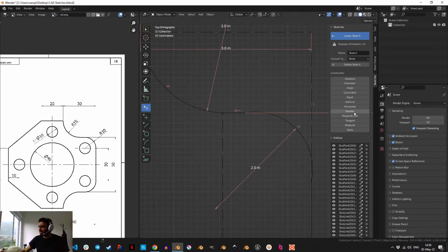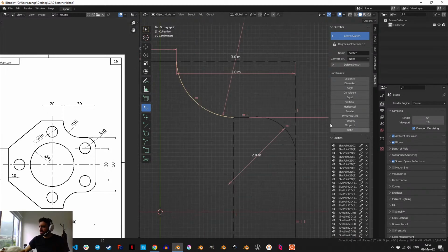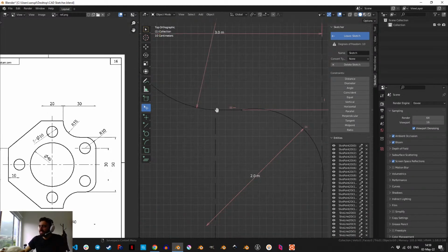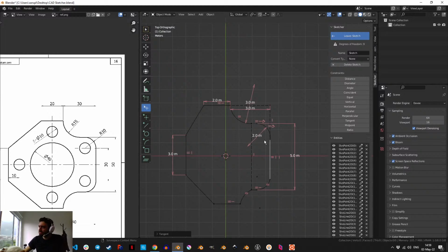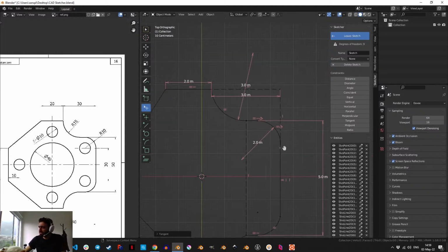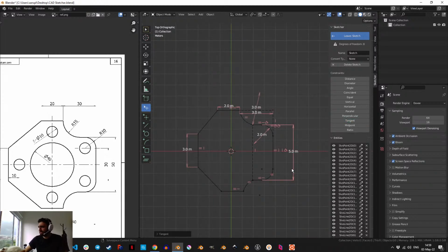Let's do it again. So tangent between this and this. Why isn't it working? Hmm. This works though. Maybe it's just over constraining. That's the problem. If I over constrain things, I'm gonna get into trouble. Here, I think we should add a tangent constraint too. Here and here. Yeah, that helps a lot.